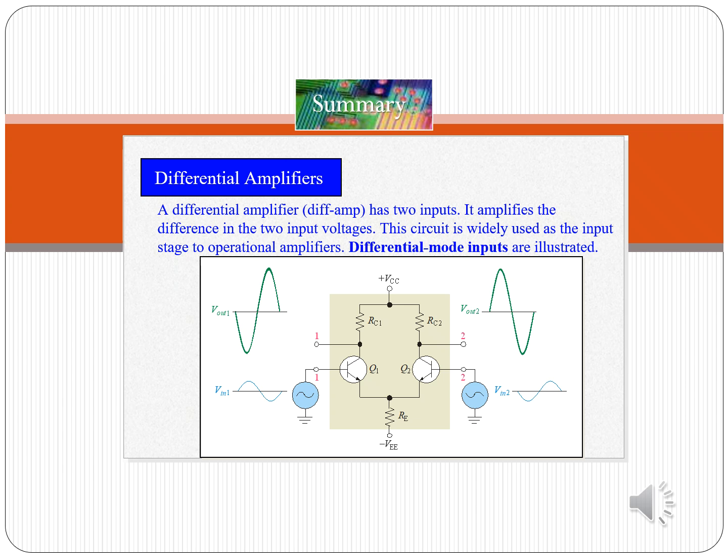So common mode noise that's felt on both lines gets rejected. Just think about what might be common to both lines. If noise is being felt by the entire circuit, you're going to have that noise on both leads, and whatever that noise is, because it's sensed at both leads, gets canceled out. We assume it's going to be noise.